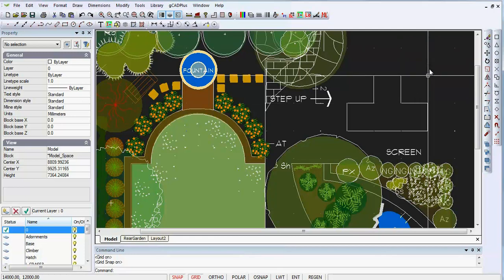One of the favourite tricks in a drafting office is to set a huge grid, turn the snap on, and when someone comes back to their workstation, they find they can't even get into the drawing at all. So being aware of the settings on these tabs down here is crucially important.